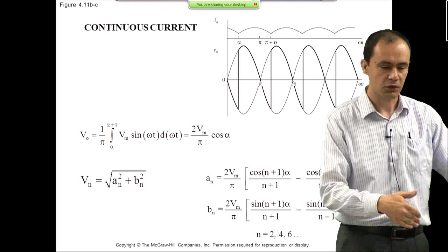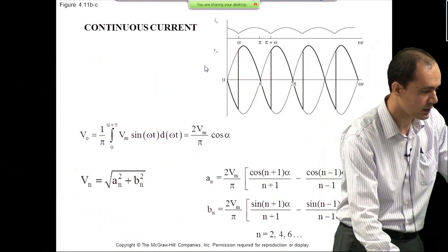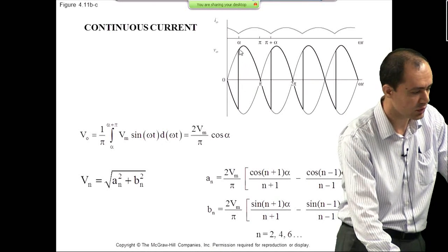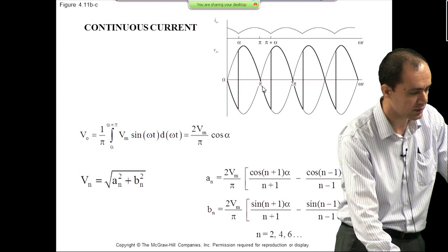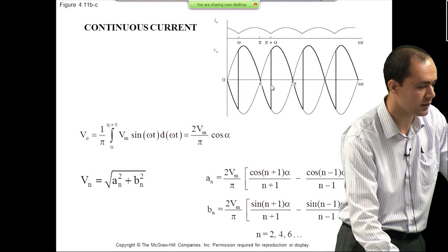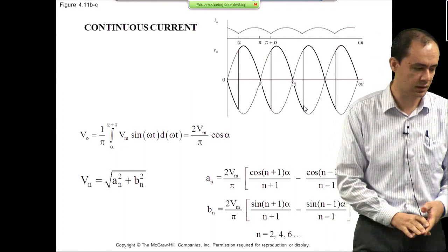It's either following the input voltage or the negative of the input voltage. Your output voltage at the beginning is negative, and then you trigger the next SCR. It follows the positive path, then becomes negative again. Then you follow the next pair of SCRs, and it follows the positive and then becomes negative, and we have a sequence like that.